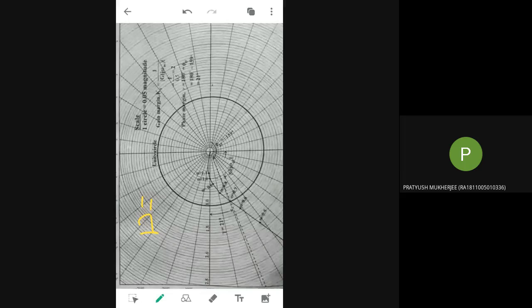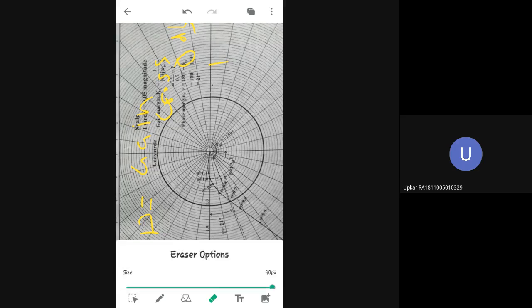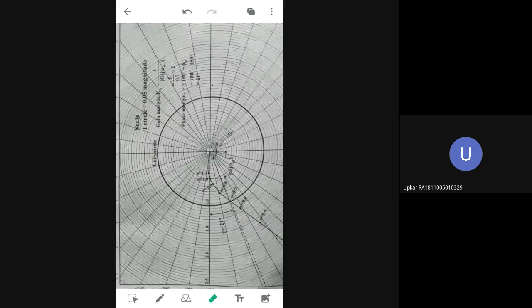Gain margin means the corresponding frequency is the phase crossover. Phase margin means the corresponding frequency is the gain crossover. Gain crossover frequency means what is the magnitude? 0 dB or 1. But here you are not taking the dB scale. You are taking ordinary magnitude. So what should the magnitude be? The magnitude should be 1, so 0 dB or 1. You remember that?